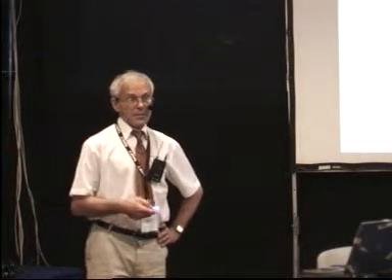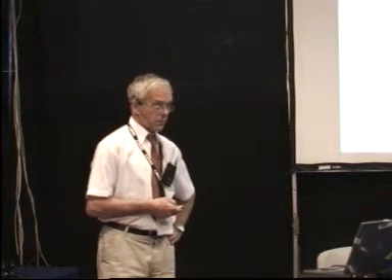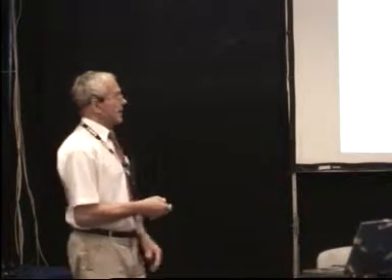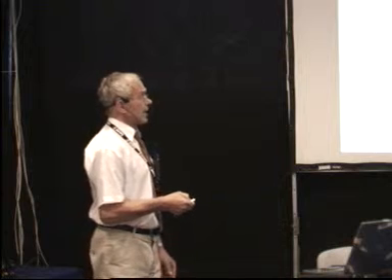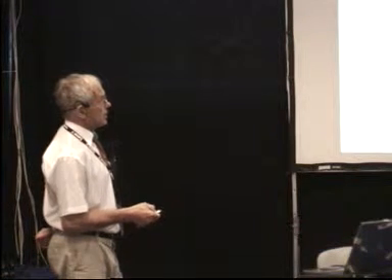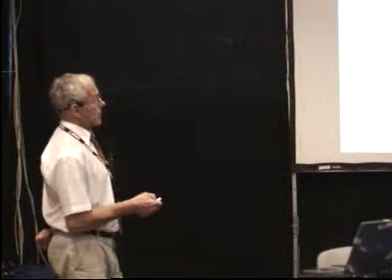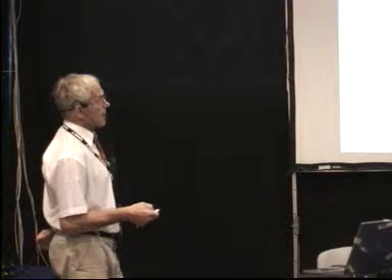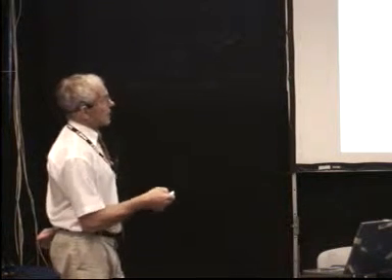So if you launch 2 or 3 waves into a nonlinear device, either in the microwave region or in the optical region, they simply mix together and create an idler. So this is the idler wavelength, which can be used for wavelength conversion, because if you insert 4 waves here, then you will obtain another 4 waves which are in frequency just on the other side of the pump. The frequencies are simply copied symmetrically with respect to the frequency of the pump.